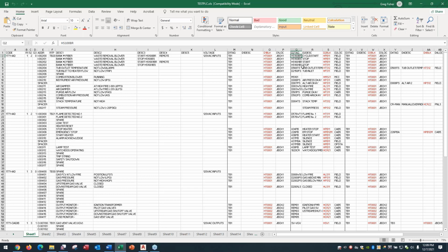Here's where somebody's tagging it. You are responsible for the tags. Now the tags can be adjusted once the drawings are created through the update retag utility. So you have to put a tag in. You could leave it blank and then run updates later, but if it's a fixed tag, because if it's going to be similar IO from project to project, most of the time it's going to be the same. But I have seen people use this utility where they will put a tag in, but then once the drawing gets created, they'll update it to suit their standards or needs after the fact.